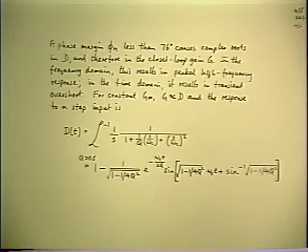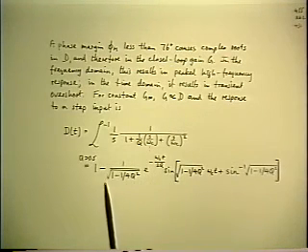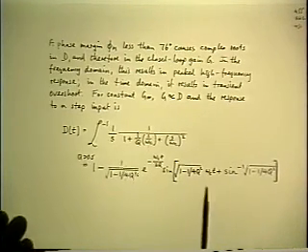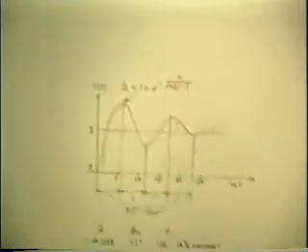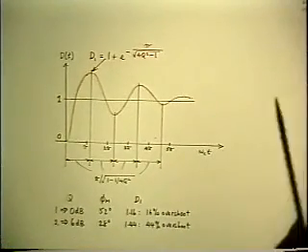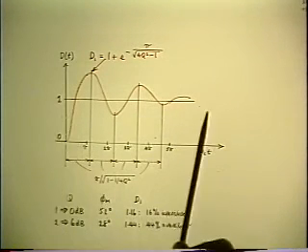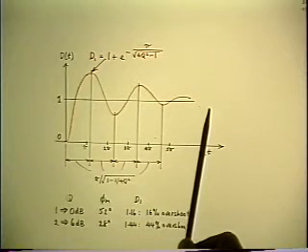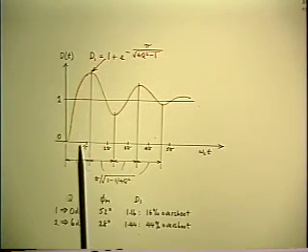So to find what that looks like, you go and dust off your book of Laplace transforms and flip a few pages till you find this one, and this is what you discover, which is a long equation, but all it says is that it's a damped sinusoid. And it looks like this, starting from 0. And it's normalized to unity input step, so that's the final steady state value of the output. And if you have a high Q, then the output overshoots and rings.